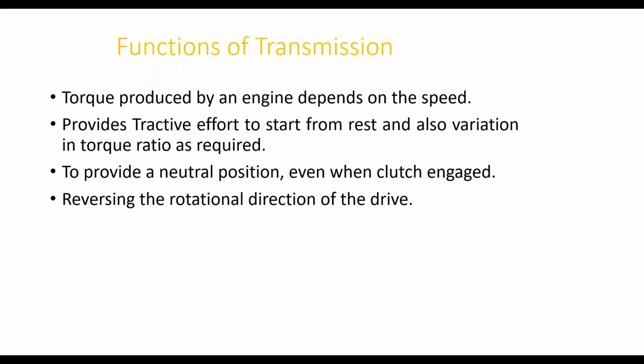And the third one is it has to provide a neutral position. When you start the vehicle, you cannot keep pressing the clutch and keep waiting. So if you want to keep the vehicle in idle condition for some reason, say for example you are parked somewhere in hot conditions and you want to run your AC, you will start the vehicle and put it in neutral. Neutral condition means even though the clutch is engaged to the engine, the wheels do not rotate.